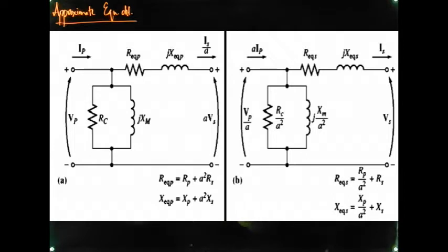circuits now. These are not now the equivalent circuits of the transformers. These two are approximate equivalent circuits, and the fact here is that these two can be obtained because of the fact that the excitation current is very low in case of a transformer. Now, having said that, even in some cases where the excitation branch is, we can actually neglect it altogether, and the circuit that will obtain because of